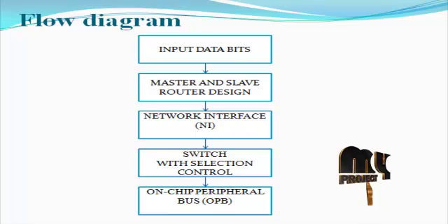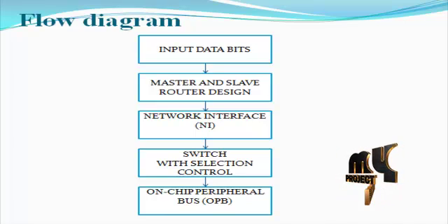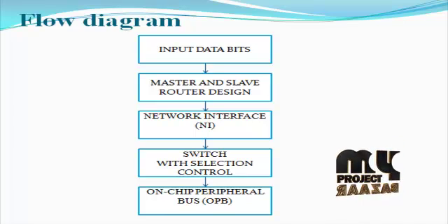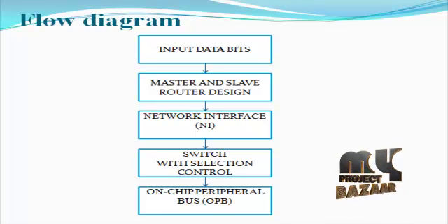The master router is mainly used to select the input for the master internal section and the output for the master external section. The other router positions are the slave router designs. First, we design every master internal and external router and the slave router for the overall 4x4 NoC architecture. Then 16 routers are combined for the overall architecture, and star based processing is applied to the central master router for the 4 routers of the 4x4 routing design.